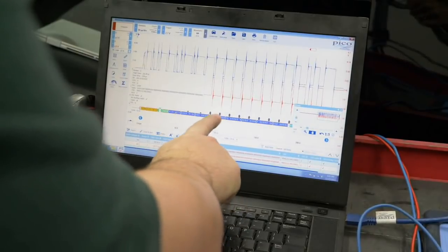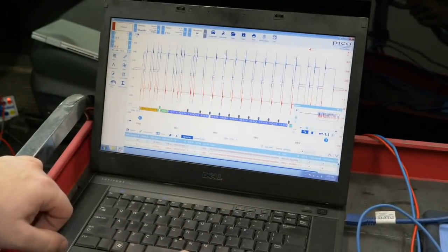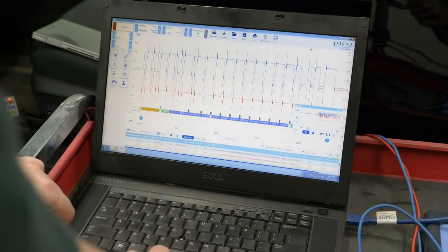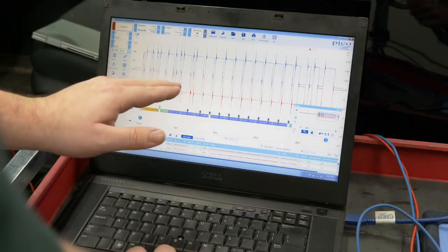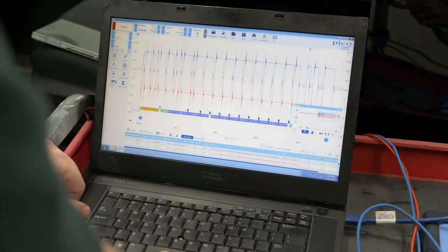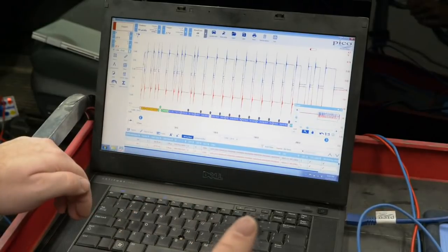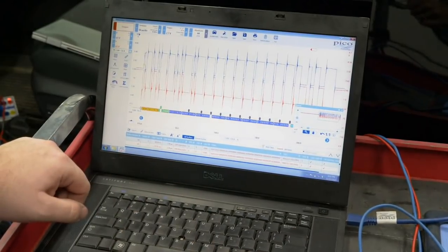You've also got these stuffed bits. You'll notice these occasional bits, and what those are for is so that the CAN bus doesn't stay silent for too long, so that each component can stay in perfect time with one another.